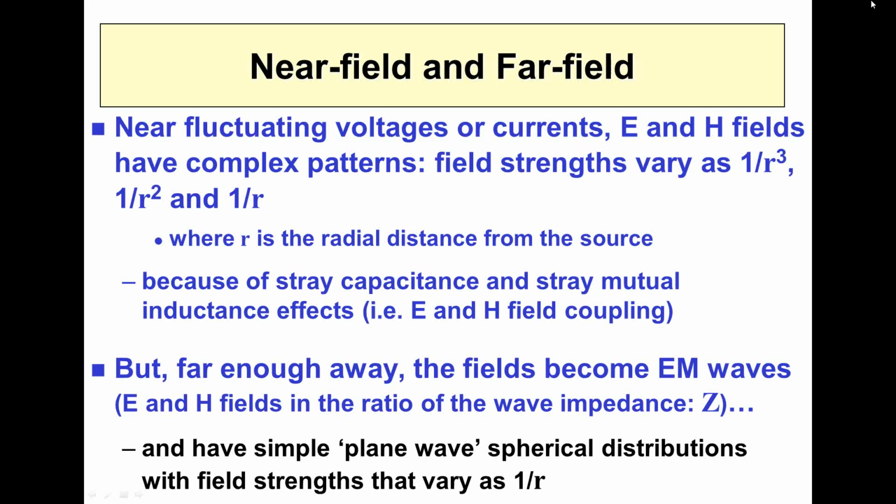Or you might take the 3 meter limit, if that's what you've been given, and measure at 10 meters with a limit line reduced by 10 dB. We're in the far field, and a lot of the measurements of fields above 30 megahertz are carefully designed to be in the far field because they're more reproducible that way.